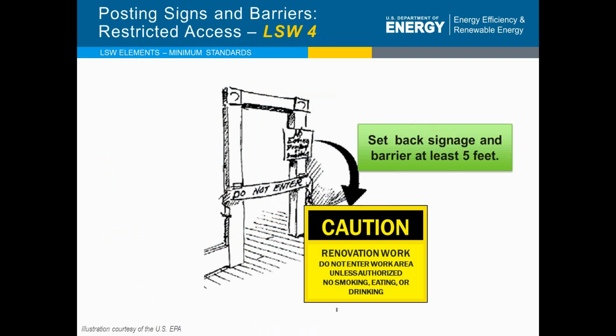Okay? Mike, two more questions. Do you know of any lead test swabs which are not producing accurate results? Yes, I do. You do not want to freeze these swabs, and you do not want to put them on the dashboard of your van during the hot sun. That will degrade the quality of them.